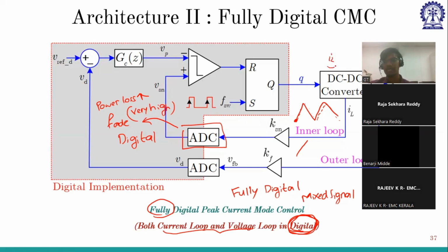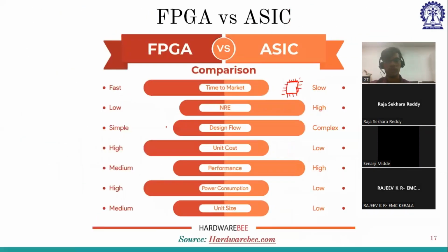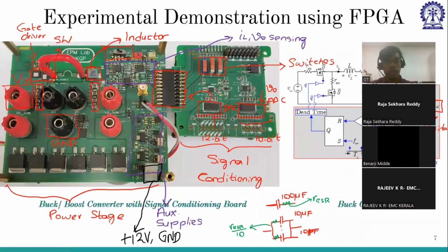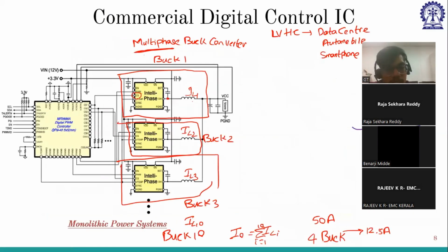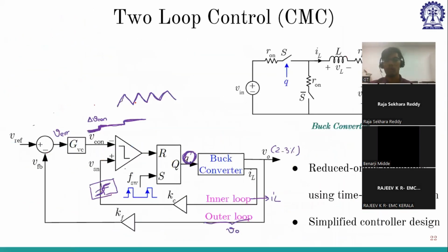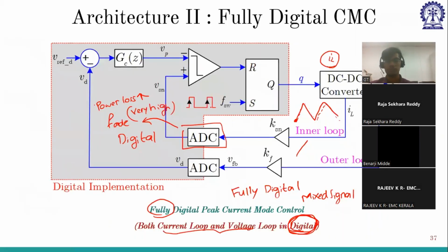So the IC that I have discussed, let me go back to that session. So here, this CS current sensing, it is going back here. So some of the ICs, they sense the inductor current and then they emulate it inside and they write the control technique or whatever modulation technique they're going to use. So it is also one such advantage that we'll be getting, and Sir will be discussing this in the upcoming sessions.